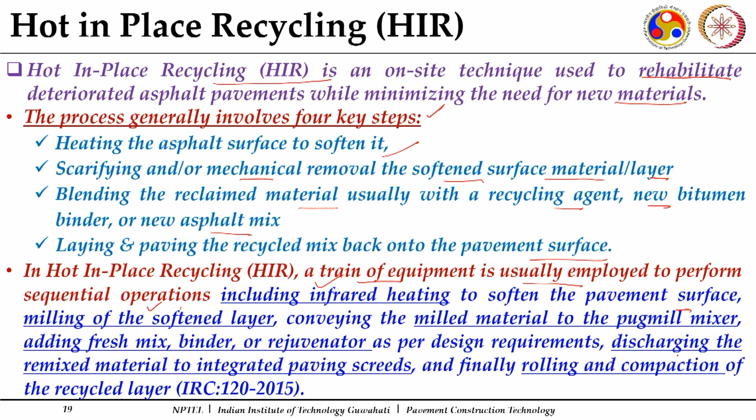Thereafter the mixed recycled material is discharged through integrated paving screeds in this equipment, and finally rolling and compaction of the recycled layer is done.